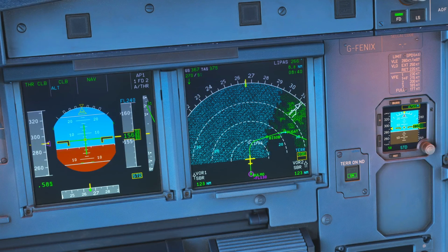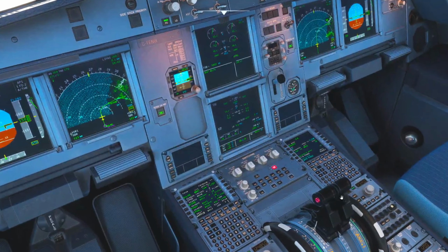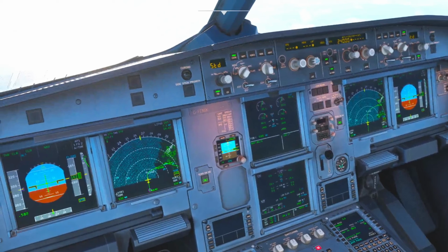To set the airspeed: the selected airspeed is used by the auto thrust to control thrust in speed mode, and by the autopilot to pitch for the target speed when the auto thrust is not holding the speed. Pull the airspeed knob to activate the selected airspeed mode.